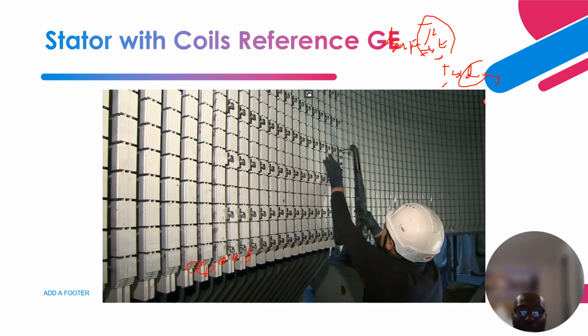Now let's talk about the end here. You can see that the end is in the form of a step ladder. It's a graded form, because the flux exits here, so you want it to be graded. Otherwise, you get a lot of heating here. That is why we have this step ladder, and at the same time it helps the faster flow of the flux and gives the flux an easier path of flow.